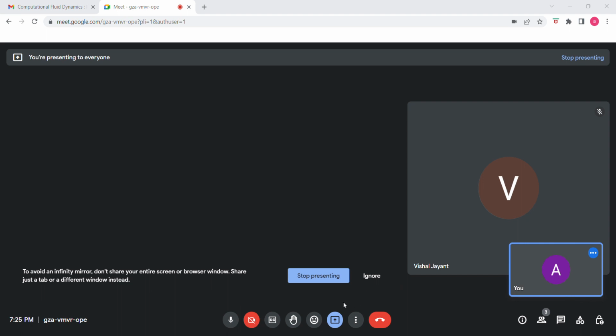We wish to solve for steady state temperature distribution in a rod of length L and the variation is only axial. Which of the following boundary conditions is true? As we know, we need values at both the boundaries. So it can be temperature at both the ends, or temperature at one end and a derivative at the other end, that is heat flux at the other end. Both of these are possible, but heat flux at both the ends or heat flux and temperature at the same end is not feasible. So the answer to this question is option 3, which is option 1 and option 4 are correct.